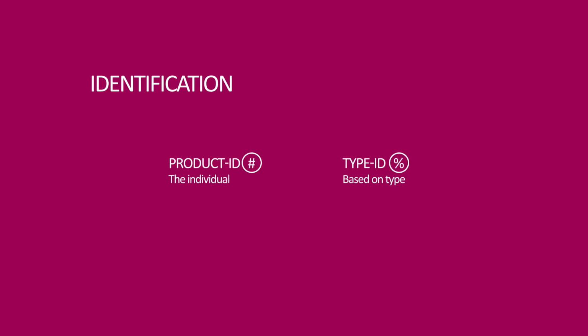CCS allows multiple types of identification. One is the identification of any building element by means of a product ID, where each building element is given a unique sequence serial number. Identification can also be distinguished by using the type level. This is when the same sequence type number identifies the same wall types. To distinguish between the different types of identification, a specific symbol in front of the CCS codes is used. In this case, the hashtag for product ID or the percentage sign for type ID.